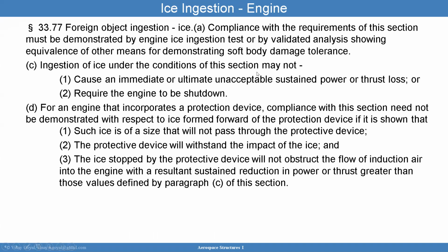Ingestion of ice under conditions of these sections may not cause immediate or ultimate unacceptable sustained power or thrust loss or require the engine to be shut down. For an engine that incorporates a protection device, compliance with this section need not be demonstrated with respect to ice formed forward of the protection device if it's shown that the ice is of a size that will not pass through the protection device. In other words, you have a way of containing the ice, and the ice is stopped by the protecting device.